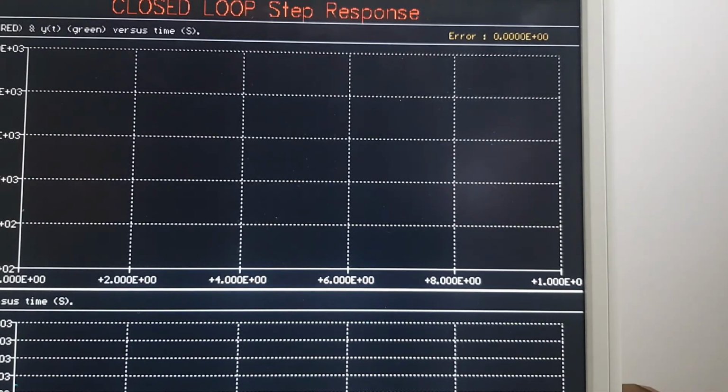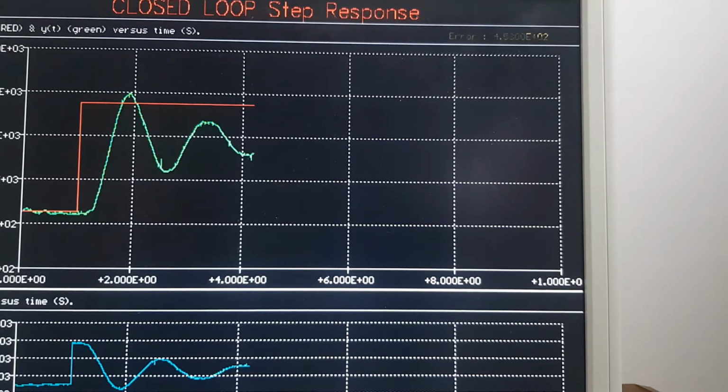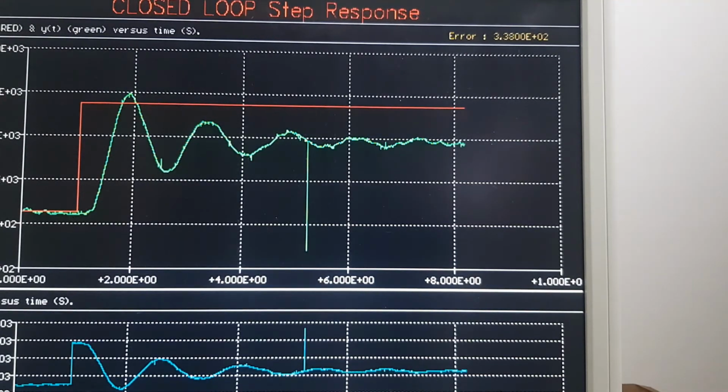If we were just having proportional on its own, this is probably what we might go for. It's a little bit oscillatory, but it's also got fairly much the smallest steady state error that we can get away with without making this too oscillatory. So that's our proportional controller.